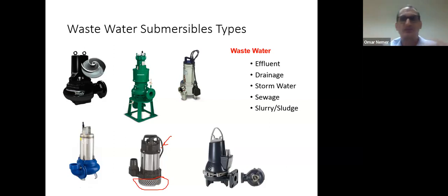I cannot use it for sewage. Now, with effluent, we are talking about particles inside that could be 8 millimeters, 7 millimeters, maybe 9 millimeters. It's very small. This is the biggest particle that can go inside the pump and be pumped out. Okay, so this is effluent.